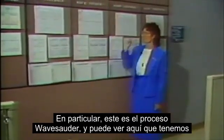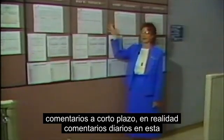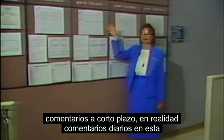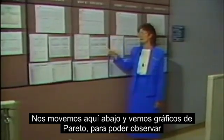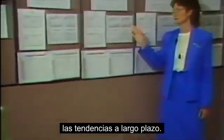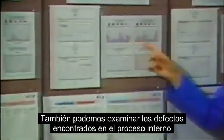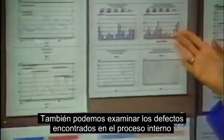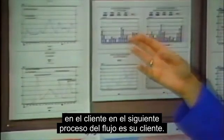In particular, this is the wave solder process, and you can see here that we have short-term feedback, actually daily feedback on this X-bar chart. We move down here and we see Pareto charts, so we can look at long-term trends over a number of weeks from week 5 to week 23. We're also able to look at defects found internal to the process and defects found at the customer in the next process in the flow is their customer.